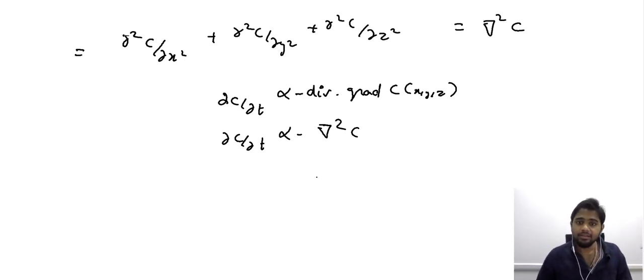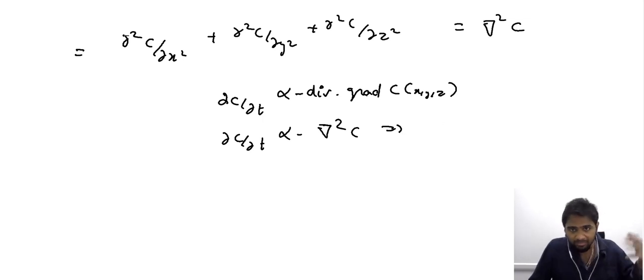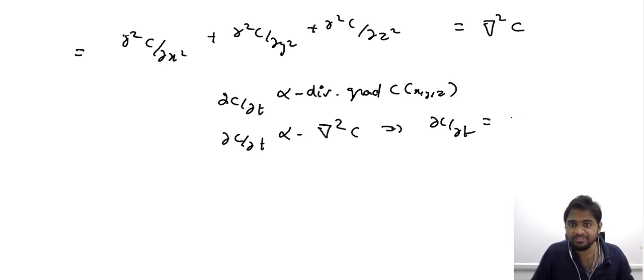And again, if we include the constant of proportionality, the diffusivity, and consider the negative sign that comes from the gradient of concentration in Fick's first law, it turns this negative sign into positive. Ultimately, after introducing the negative sign that comes from the gradient and the corresponding constant of proportionality, which is diffusivity, the expression is written as nabla square c.